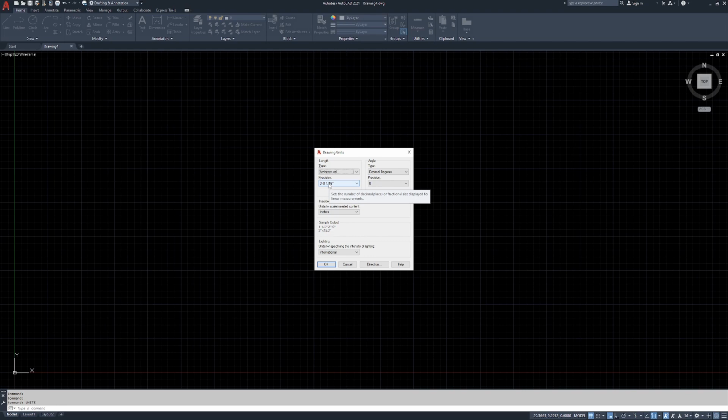that actual dimension is. So if you need super accurate dimensions, you're going to need this precision a little bit tighter. So 1/16, 1/32, 1/64, 1/128, 1/256. I don't use anything below 1/16 of an inch because that's overkill, and most of the things that I do don't involve 30-second tolerance. So for this, I'm just going to keep it at 1/16. Insertion scale, you don't typically have to touch.